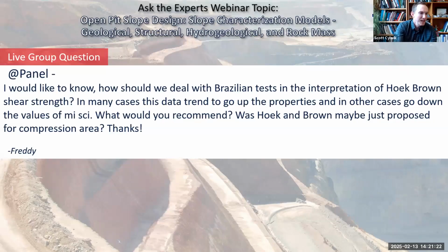So if the UCS or the Triax test comes back funny, if it comes back suspicious, if it looks like there could be a problem with that piece of core, now we can go and check the tensile value of the cutoff from when we were trimming that sample to see, was the tensile value from the cutoff also strange? Or was it also very strong or also very weak?